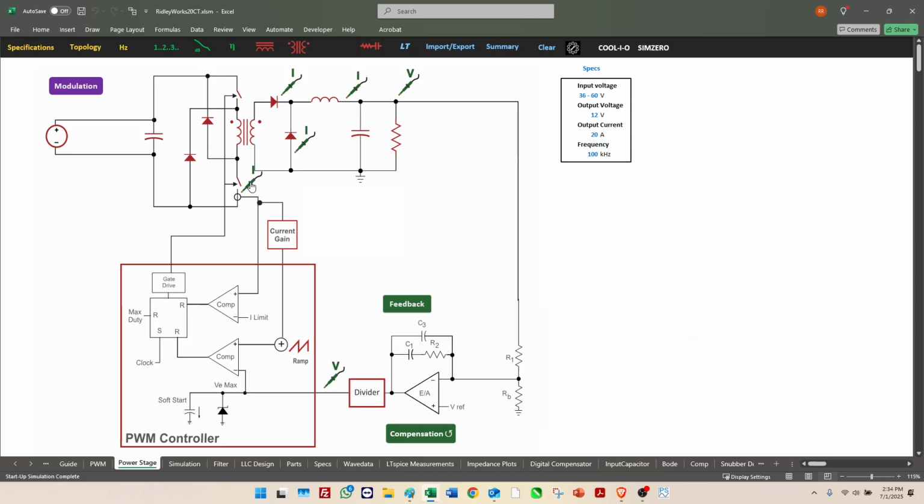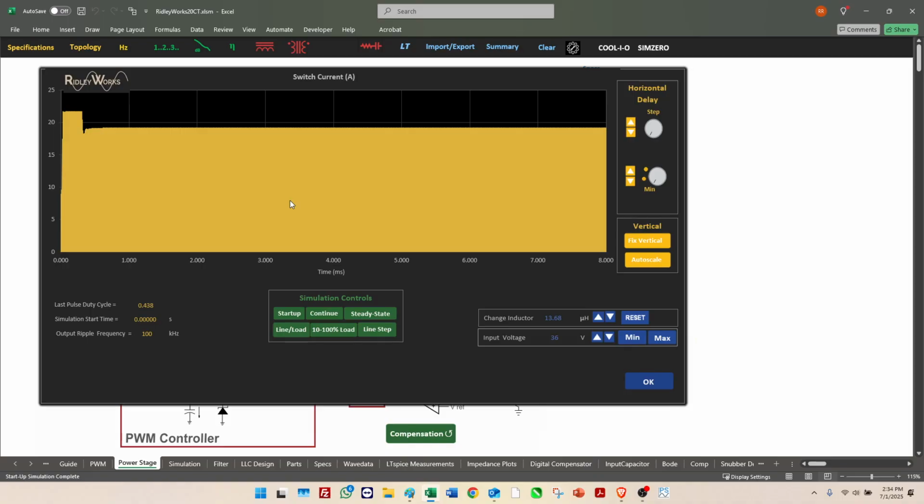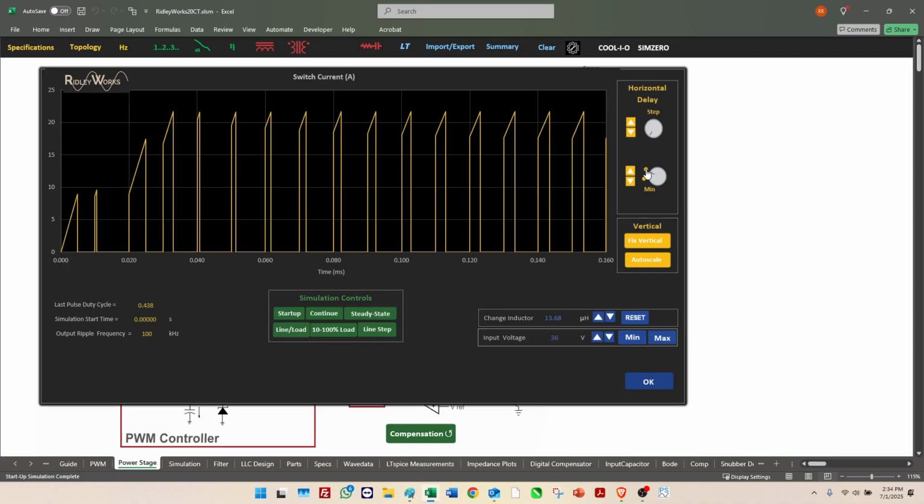And if we go look at the input current here, we can see just a continuum of waveform because the resolution of the screen can't show all the cycles that we've got. So let's zoom in a little bit by turning the time-base dial. And now you can see the individual cycles of startup. So here it goes maximum duty cycle, then a minimum. That's almost like a subharmonic oscillation on the way up. Then it goes through a maximum duty cycle, another one, and then a small, narrow pulse.